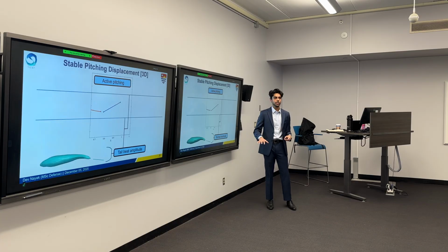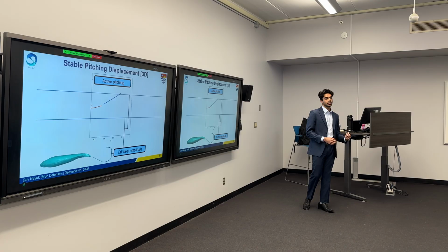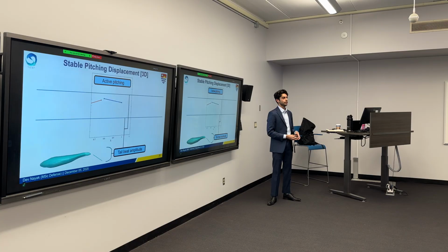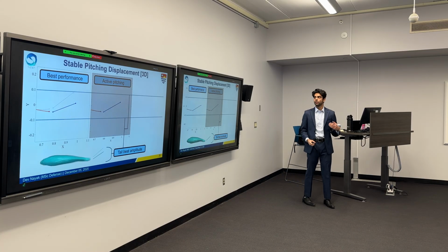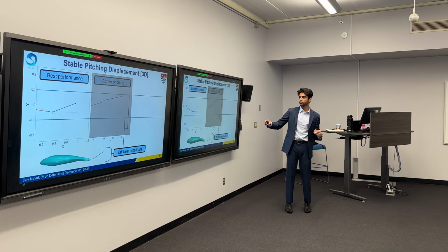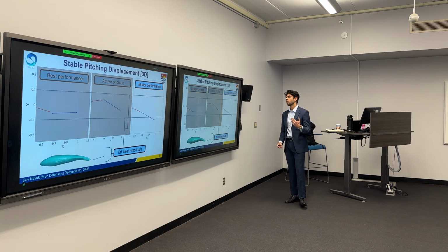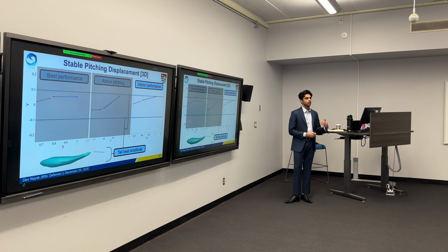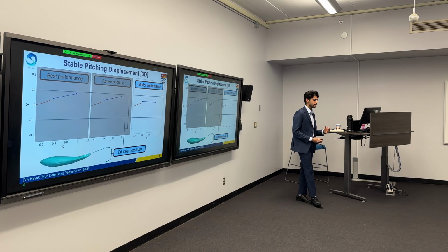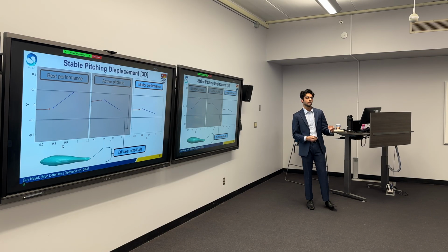The actively pitching tail is designed and modeled in a way that it follows a very close kinematics to the Carangiform swimmer itself, and it does not really leave the range of the tail beat amplitude for the Carangiform swimmer. When we look at the best performance case, which is at lower zeta, here we see that the tail beat amplitude follows a very exact similar resemblance to the actively pitching tail. Now, when we move on to the case that shows inferior performance, the phase advance actually goes to a very large amplitude. Now, that does create larger vortex activities in the wake, but that does not necessarily contribute towards thrust, and we'll see that further.